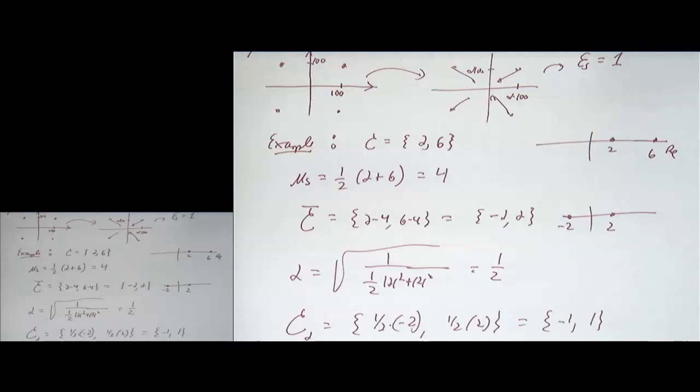You won't even see this normally in an advanced course either. It's just not needed. The only place it comes up, to my knowledge, is in voice band modems. And there they have a very special coding structure to create a set of constellation symbols that are not equally likely. It's really cool, but it requires a very complicated decoder. They do that because they have to get so close to capacity, they need that extra little bit of complexity. And we just don't need it in wireless. I suppose we could use it, but it's unused.